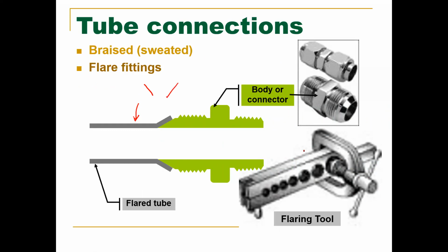That's this piece right here. This tool is a clamp with another V in it. You put the piece of pipe into it, and as you apply pressure downwards, it will form out the tube so that it's flared.